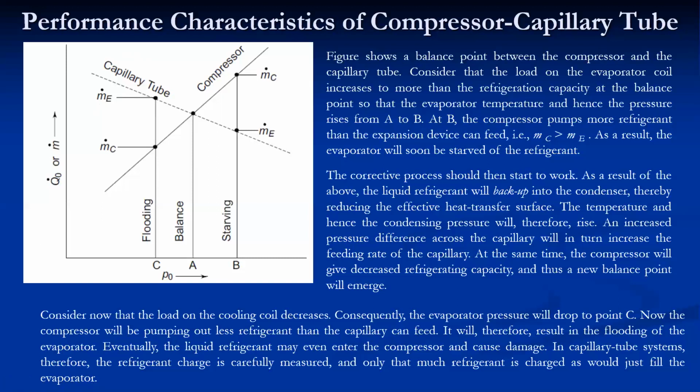Now, what will happen in this case? As more refrigerant is entering the evaporator and less refrigerant is going out of the evaporator, the evaporator is flooded with liquid refrigerant. So this is a condition which generally arises, and it will therefore result in flooding. Eventually the liquid refrigerant may enter the compressor. There is a possibility that the liquid enters the compressor and can cause damage.